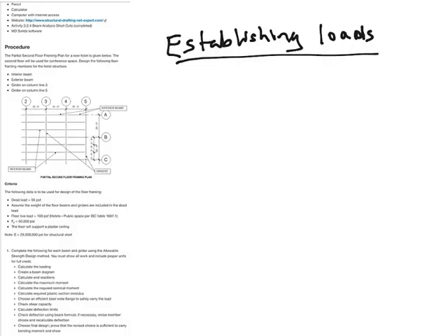All right, I'm going to cover establishing the loads on an interior beam in this video. When we have an interior beam, we're talking specifically about these beams in the middle here, which are all interior beams. We're going to have to establish the tributary width and then determine what our design load or loads are going to be based on the criteria here.